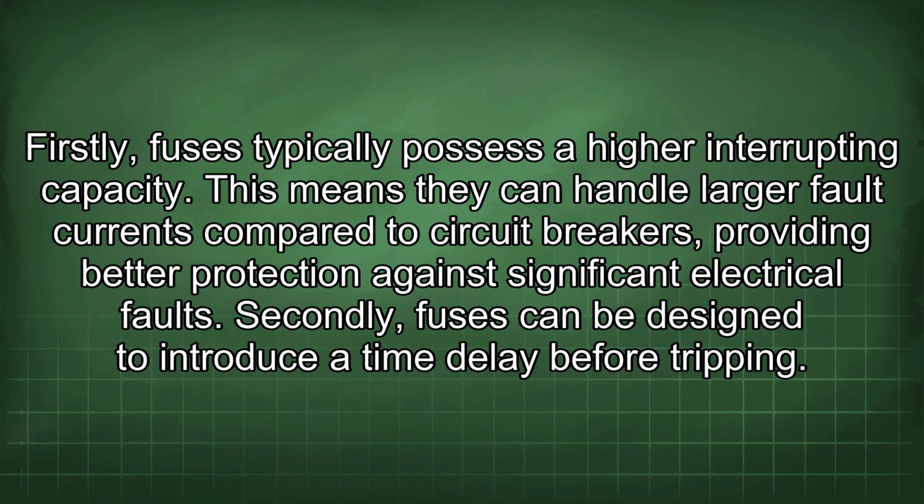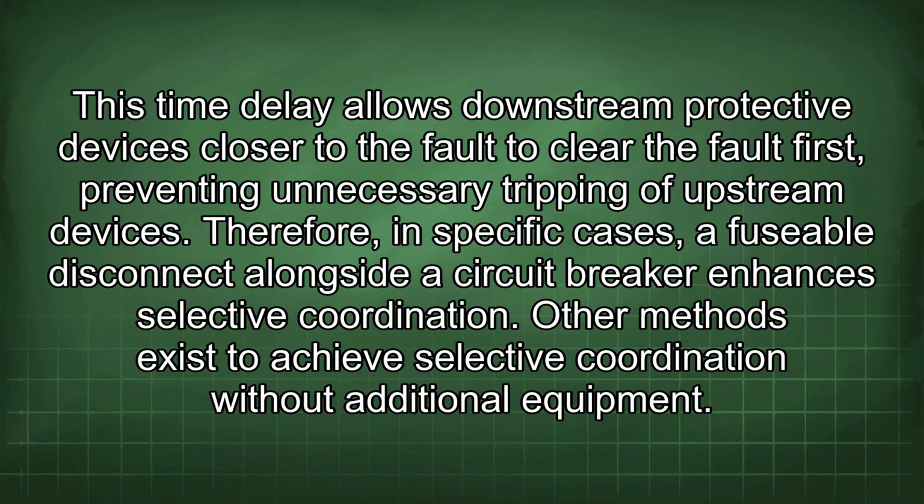Secondly, fuses can be designed to introduce a time delay before tripping. This time delay allows downstream protective devices closer to the fault to clear the fault first, preventing unnecessary tripping of upstream devices. Therefore, in specific cases, a fusible disconnect alongside a circuit breaker enhances selective coordination.